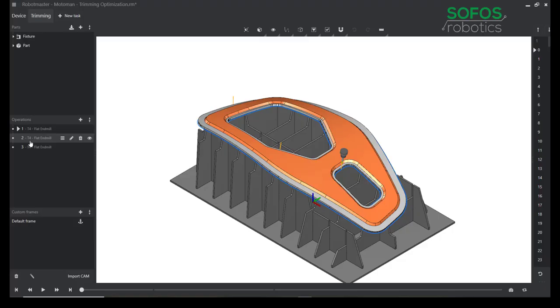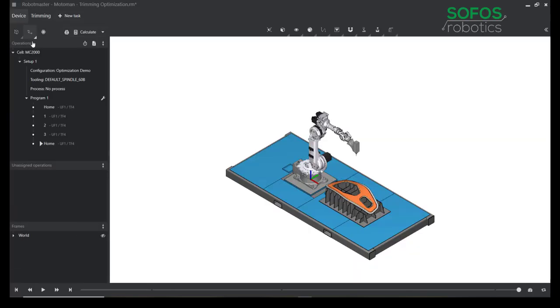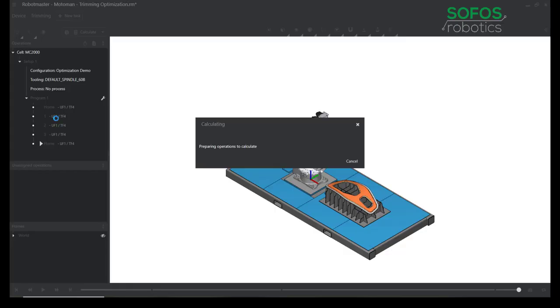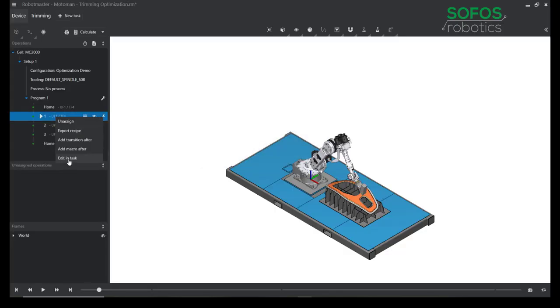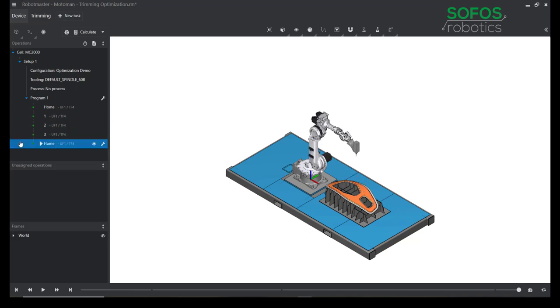so that later, if I'm doing more paths that are going to be the same parameters, I can just go in, click the path that I want, click OK, come out here, right click, and then there will be an import preset. And then we just import that preset, and it automatically sets all of the parameters for that toolpath. And we also have that on the device side as well. You can create what's called a recipe. So export recipe here, name that recipe whatever makes sense to you, and then for subsequent toolpaths, you can import that recipe. So once you get your library set up, it really becomes a matter of clicking where you want your toolpaths, importing your presets, importing your recipes, and you're ready to post the job.